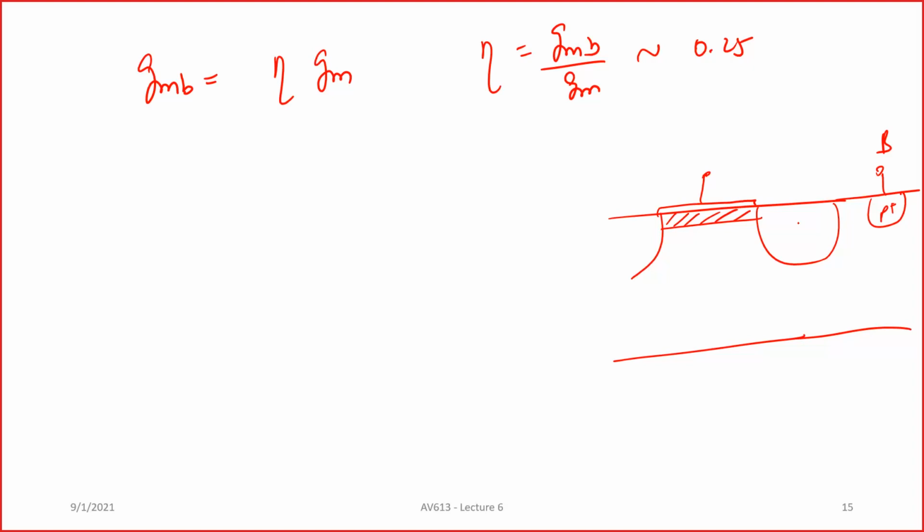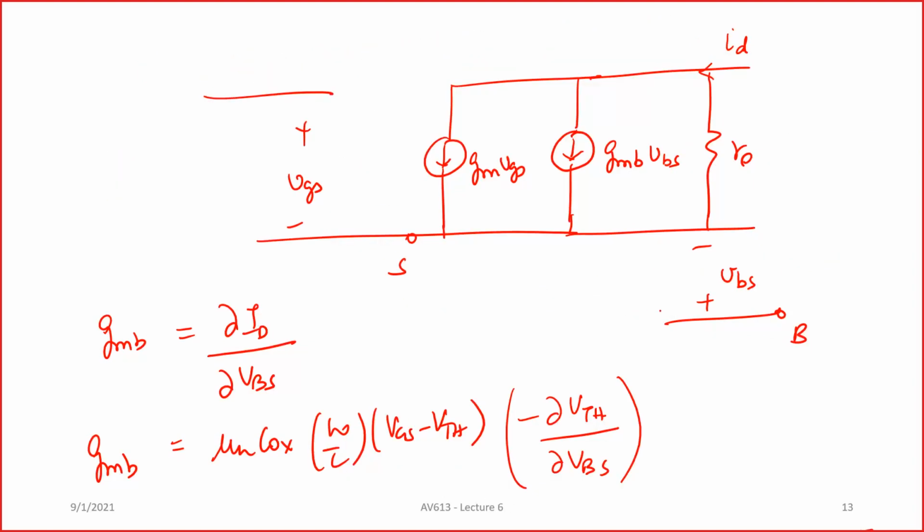Here your gate potential is there. Sometimes they call it the back gate. Of course, the inversion channel forms, but it is dependent on both these potentials. So it is almost like a second gate, which is why I was trying to justify why you put two current sources together, GM and GMB. That was the analogy I was trying to have. Okay, all right. Yes, sir.